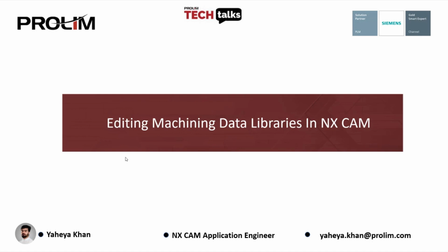Hello everyone, welcome to PROLIM Tech Talk. Today we'll be talking about editing machining data libraries in NX CAM. Well, this is a very short topic, but again it's very useful. You can predefine your speeds and feeds with the help of machining methods, tool material and part material. Let's go ahead and take a look at our NX and see how we can edit those data libraries, as well as how to locate the files that are saved inside the NX directory.